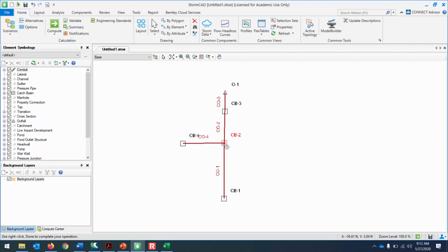And that's why when I was here at 2, I then didn't go to the left, because then it would think that the water goes from the left towards that other junction. So that's why I went in a straight line, and I was always building the network downstream.